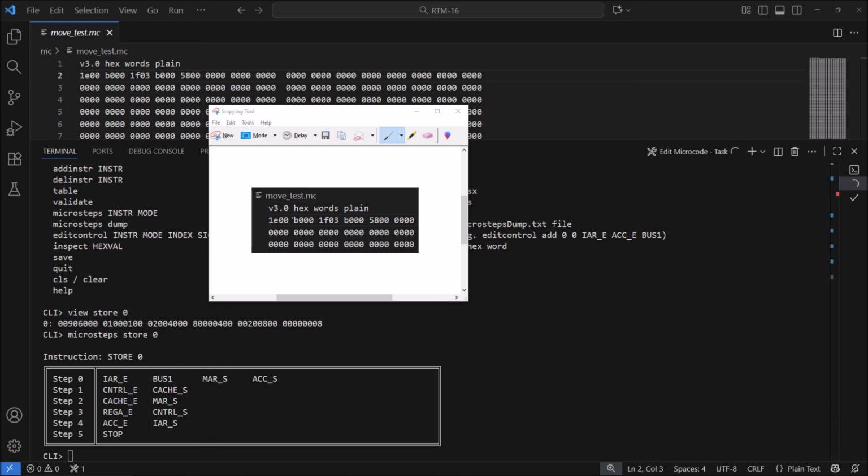But we've still not got access to the actual position here within the memory. We've only got access to the 0x8001. So we're going to enable the value B000 onto the bus, and we're going to set the memory address register again. So we're actually going to have access to now the memory location B000.